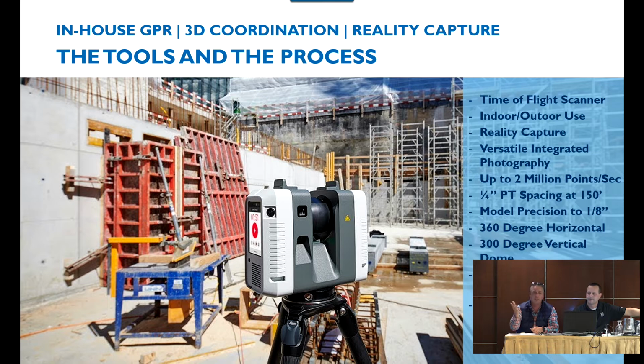It will spend 26 seconds inside of here, and it'll capture 2 million points per second. So what you see in the picture here is not far from what you would digitally see once you scan it and import it into a drawing. It does the photography, and the nice thing about it is it does recognize georeference targets. So we'll establish our targets within this room, we can scan it, and the software then recognizes where we are. So then we can incorporate it into our coordinated model.